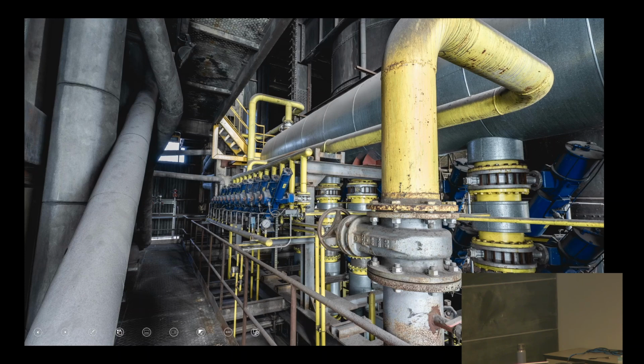So we have some other types of valves here. These look like control valves. Does anyone know what type of control valve this is? This looks to me like a butterfly control valve. It's a very thin valve, and there's basically a circular plate in there, and the plate just rotates. When the plate is completely blocking the flow, it's basically stopped. When it's completely sideways, that's fully open. These look like some sort of actuators that would be used in a control room, so this is a remotely actuated control valve. This system is able to be controlled remotely.